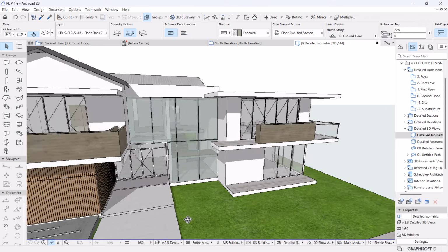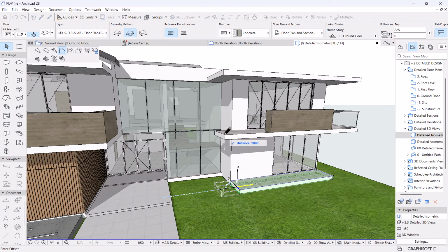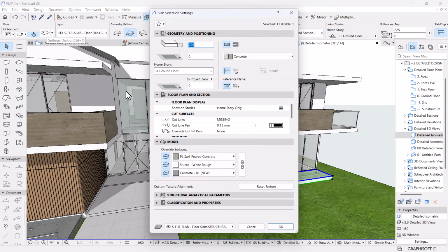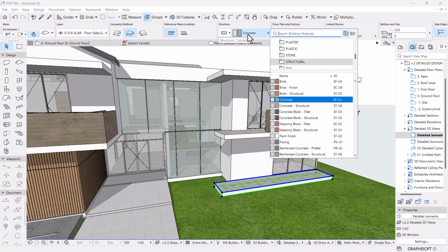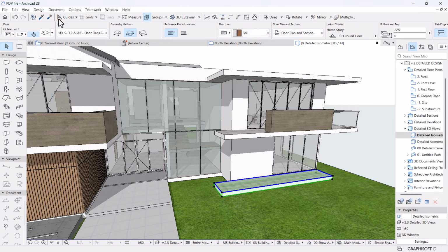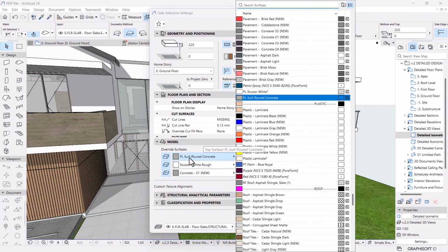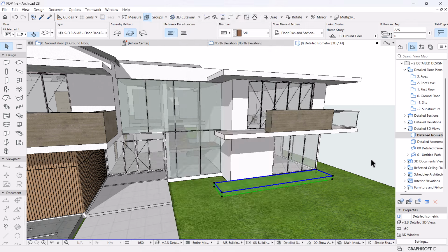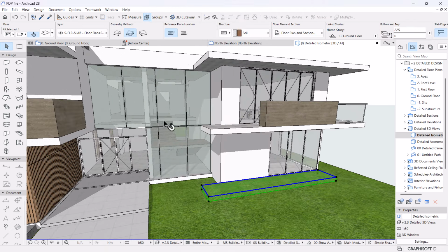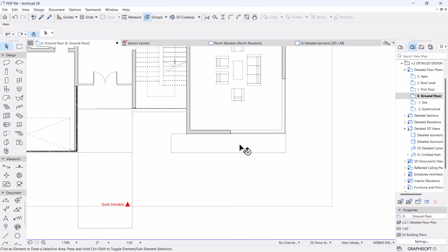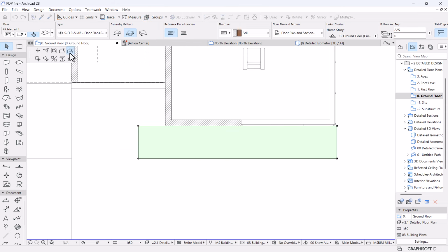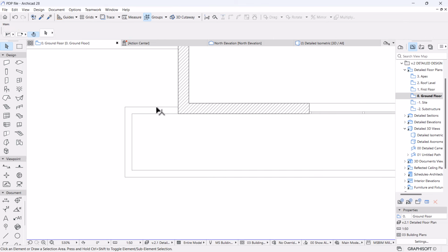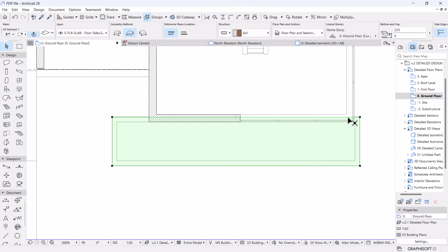It needs to be at the level or aligned with this edge. And then I'm going to change this to be grass, change this to be soil, and let's make the surfaces grass. Perfect. And then what we need to do is to have the walls around our planter, so I can just manipulate this and add a copy, subtract an offset copy, make this 150, which is the thickness of our wall. So the wall is going to be trimmed